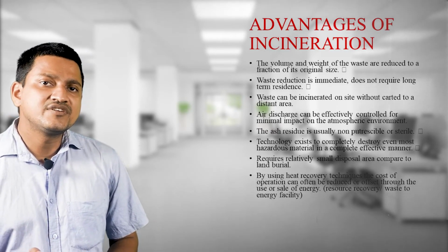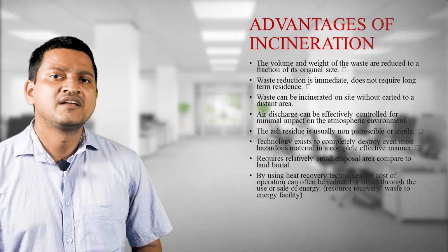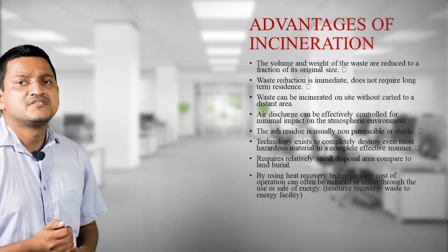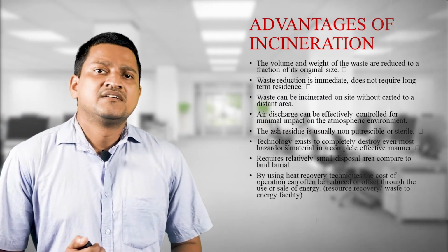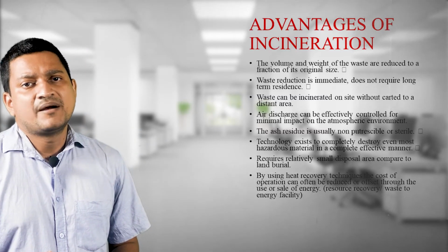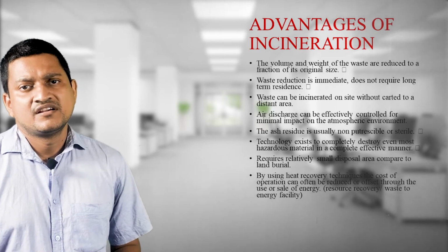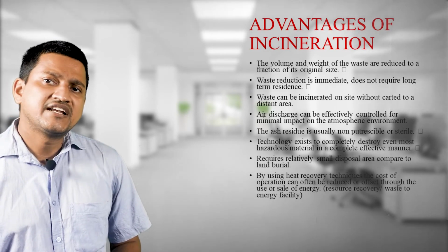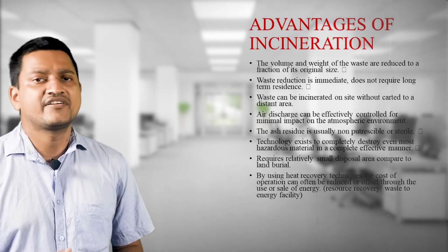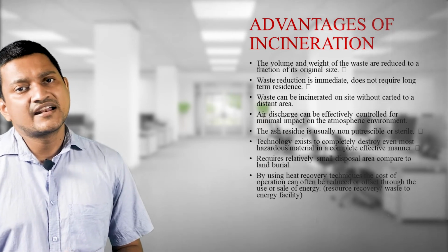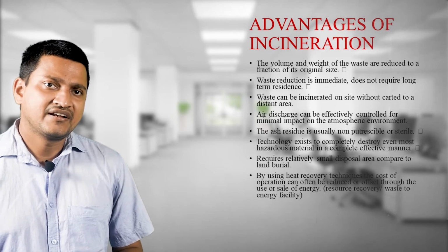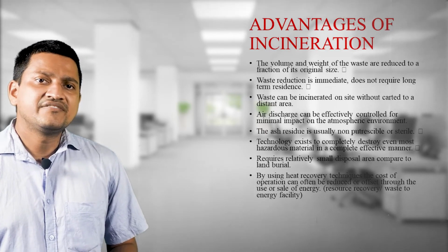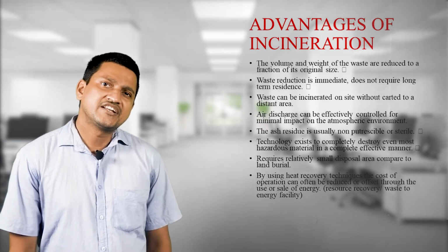The ash residue is usually non-putrescible or sterile. Technology exists to completely destroy even the most hazardous material in an effective manner, and it requires a relatively small disposal area compared to landfill. These are the different advantages of incineration techniques.